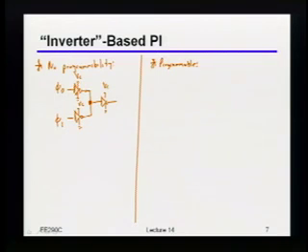Break the inverter down into smaller inverters. Make the total width the same, and turn on the number of inverters based on the programmable codes. Yeah. Okay. So then, how do you do that? You're absolutely right. You take the two inverters, you split them into smaller pieces, and then you turn on those smaller pieces in different ratios, either looking at clock 0 or clock 1, depending upon the digital code. But what's the hardware I need to do that? What do I have to hack in order to get that to happen?